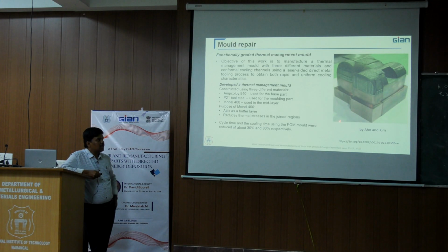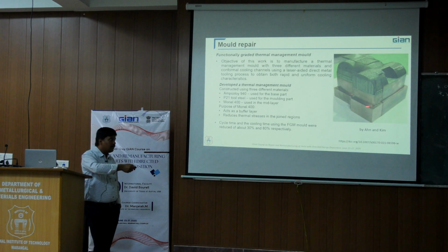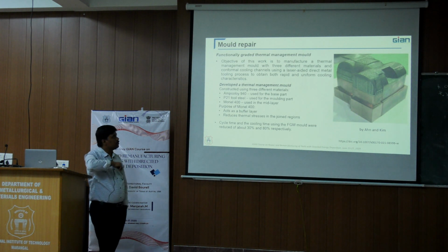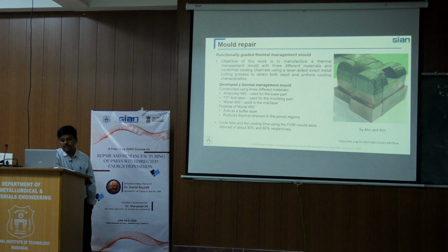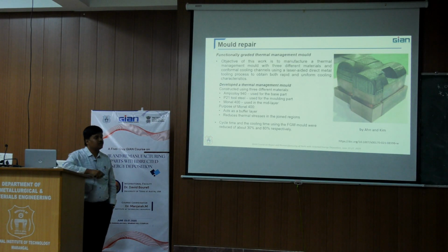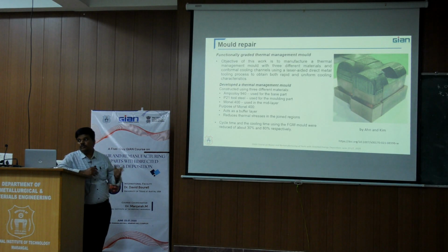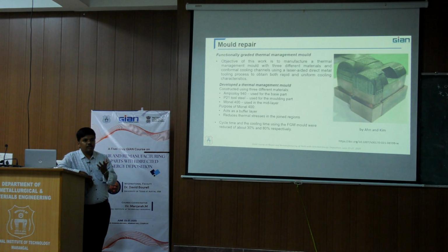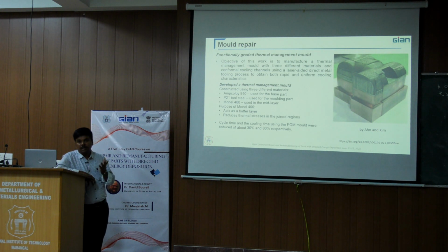And if you see, another aspect is the bottom is copper and the top is some kind of tool steel material deposited. That's the H13 deposited on the top. This is required because when you use it for die industry applications, we need to provide a lot of cooling. Otherwise, die damage is going to take place. Because copper has high thermal conductivity, it will dissipate heat very quickly compared with other materials. But on the top surface, we need a very hard material which also has high strength.